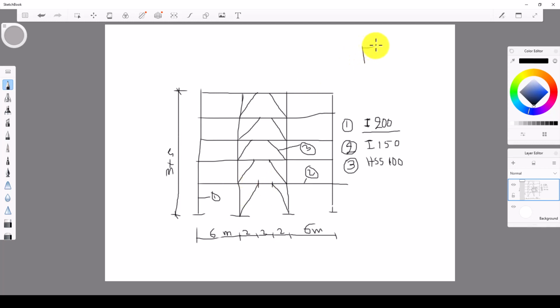And if we go to the concentrically braced frame, you can see here there is no link or arm. So this is concentrically braced and this is eccentrically braced. So this is much more ductile and also more complex than the concentrically braced frame. So it's utilized for earthquake areas with high seismicity, as well as for high-rise buildings, and this is a better system than the concentrically braced system.